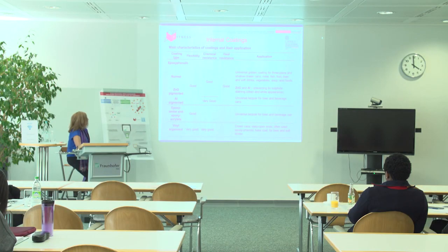Okay, and here are some examples of the coatings. We have a major class, epoxy phenolic, epoxy plus phenolic. So it's like a polymer. So we have some epoxy and some phenolic, and therefore we can have a range of lacquers depending on the proportion of epoxy and phenolic.